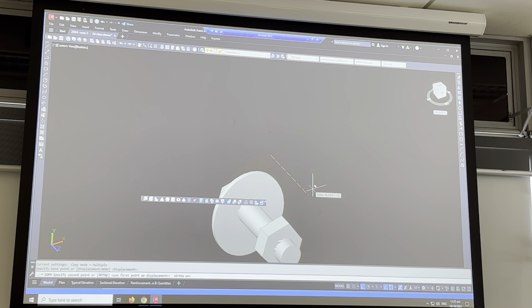It's got kind of two arms. And when you tighten up the bolt on the top, the nut, it pushes those arms out that way and that way into the concrete, which holds it all in, you see. And so I don't need to see that in 3D. I'm just giving you an idea of what it looks like. And when you're doing your plate detail, you're looking down on it, so I don't need to see all that either. Okay?